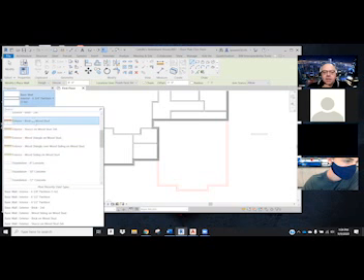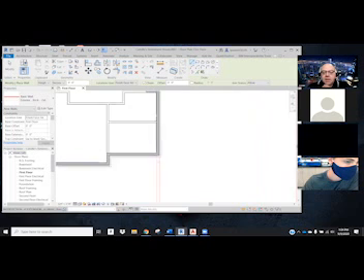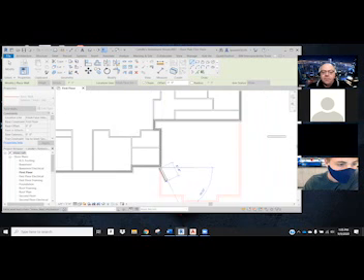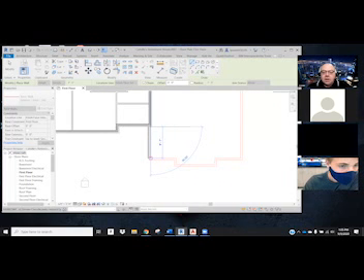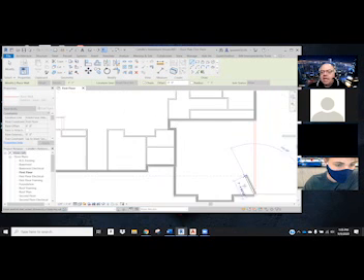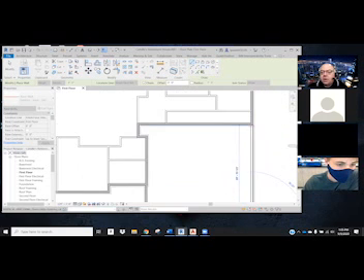And it's the brick on 2x6. I'm going to go off of the finished face interior. And I'm just going to flip that wall as needed. You know how to do that now. Space bar. I'm just going to trace off the walls that I have not done for that garage. And I know some of you pick plans without a garage. That's fine. If you decide to add a garage later, you are welcome to do that.